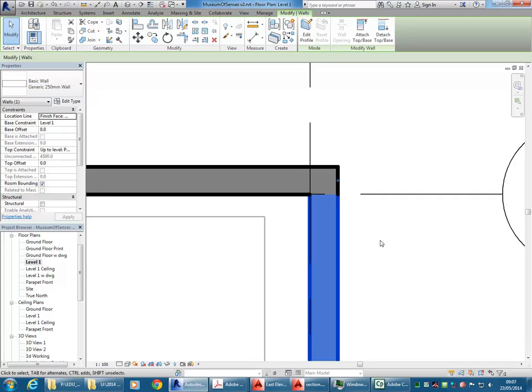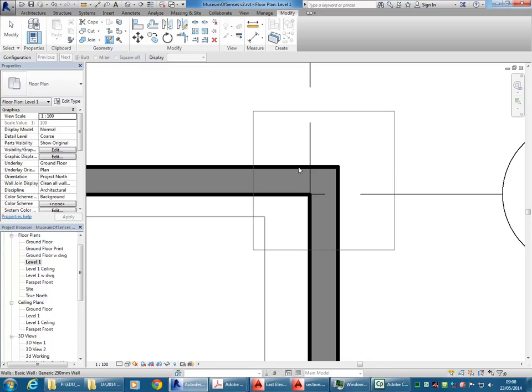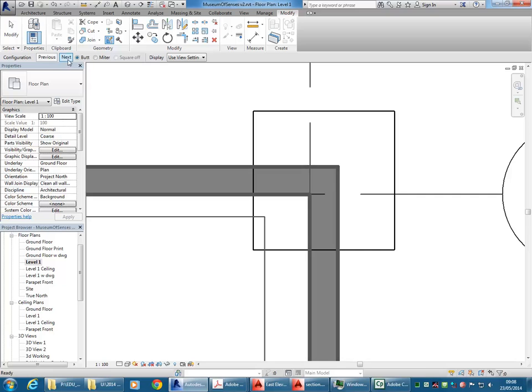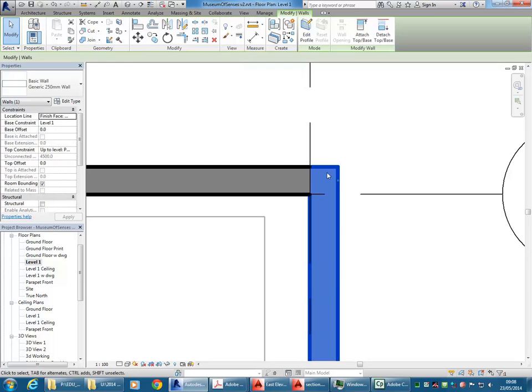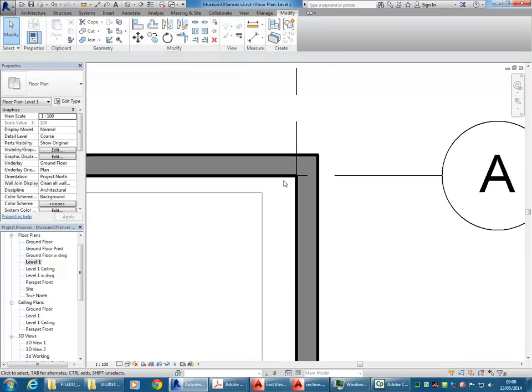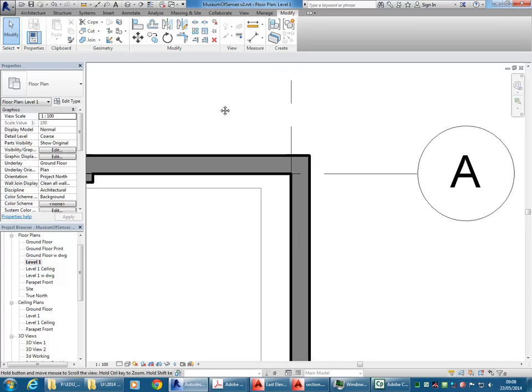With the parapet, we want it to go all the way to the edge, so we can edit the shape that we need. So I'm going to again go back to wall joins, and then clicking on that corner there, you can see this boundary line that comes up. So that's showing me how this wall extends to the end. So I'm going to leave it on but then go to next, and you'll see now the boundary line's gone to the left, and it's clear through from the front wall. So that's done, and then again if I select this wall to check that it's working, it goes all the way to the end now. And so you can do that with any wall, or any two walls that join.